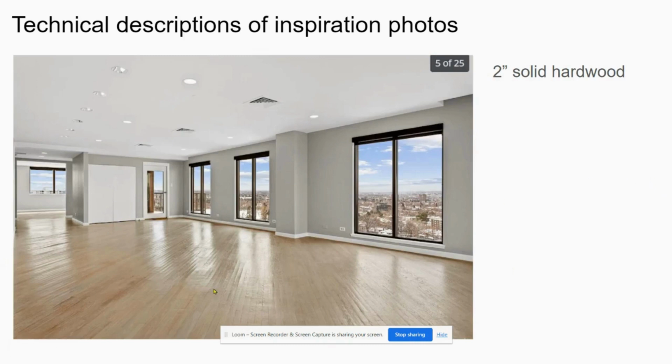In this photo, we're talking about the wood floor right here. This is a 2-inch solid hardwood. Actually, it might be a 3/4 inch, but I put 2-inch. I'd have to measure it to really know, but it's 2 inches or less on solid hardwood because it has these tiny little wood planks, whereas for engineered hardwood, the smallest would probably be a 4-inch or a 5-inch wood plank. So if you're looking for those tiny, really thin, narrow wood planks, you have to use solid hardwood.